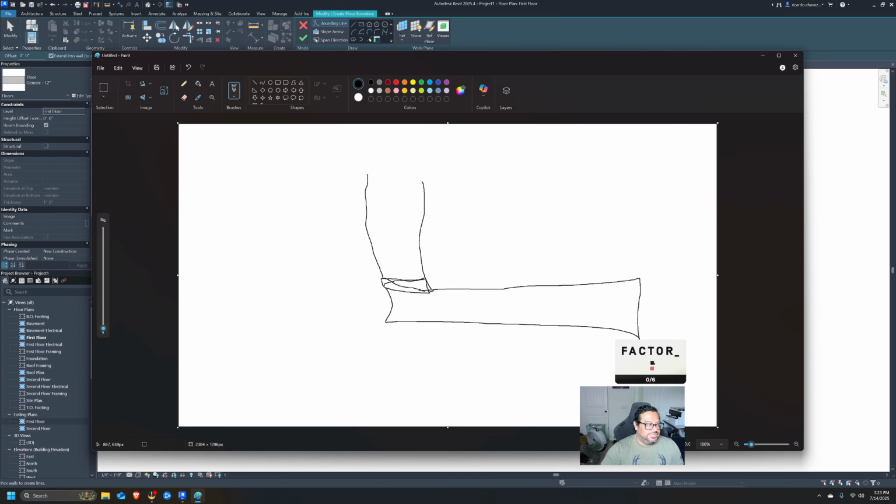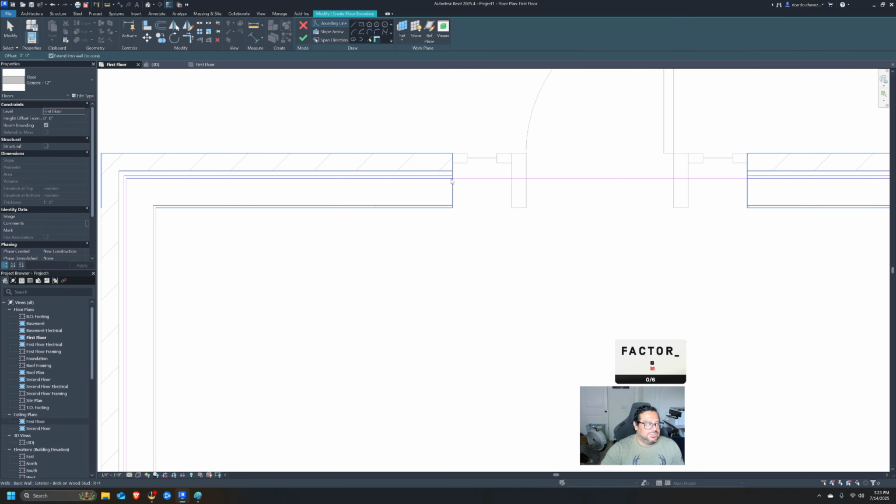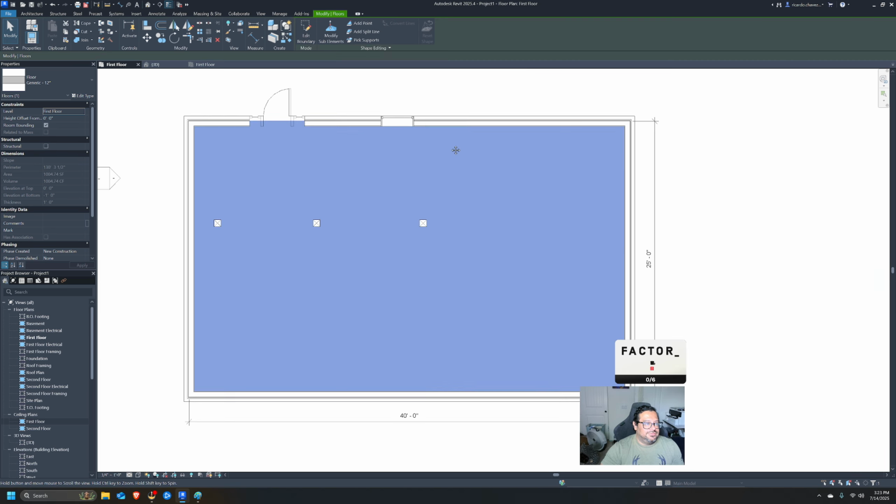Your finish and all the exterior stuff is going to be over this concrete. So in Revit, when you're doing a floor, if you pick the wall to choose, it's only going to do the floor to your interior structure, right? And that's what you're seeing here. You're seeing that it's only going to where the stud is. And that's a floor. So that's the floor there.